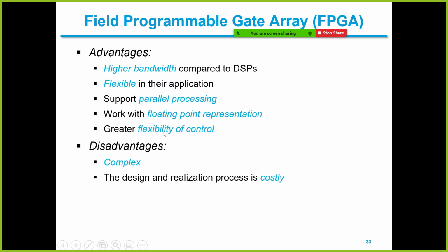The advantages: FPGA has higher bandwidth, and is flexible in application, right? It's really programmable, really configurable. It supports parallel processing. It works with floating point representation. Yeah, more flexible. The disadvantage is that it's complex. The design and the realization process is costly.